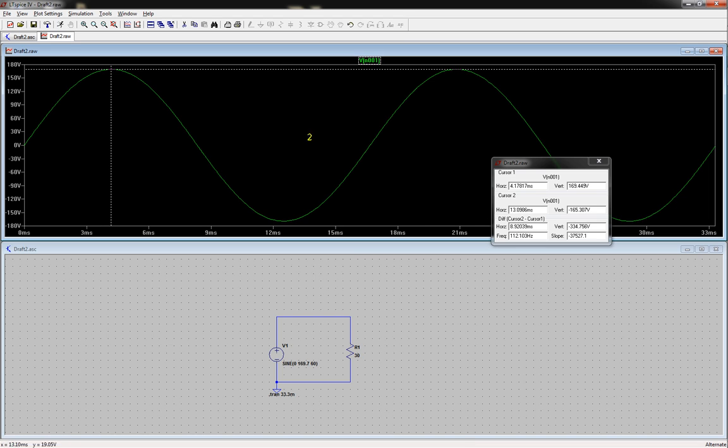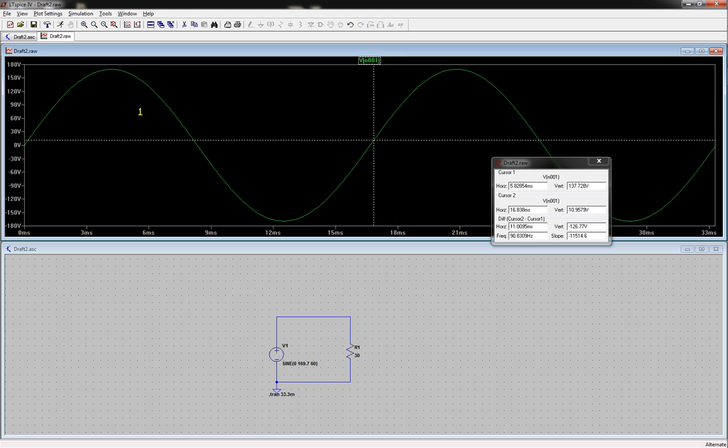And then, of course, we run it up here. We should have close to 0, which, yeah, we got 23 millivolts, pretty much close to 0. They're basically subtracting because they're both equal. But another thing that would be helpful is, let's say we wanted to know the timing between here and here, and there it is. It's about 16 milliseconds. So that's 2 useful little tools to use, these different little cursors, which are nice to have.